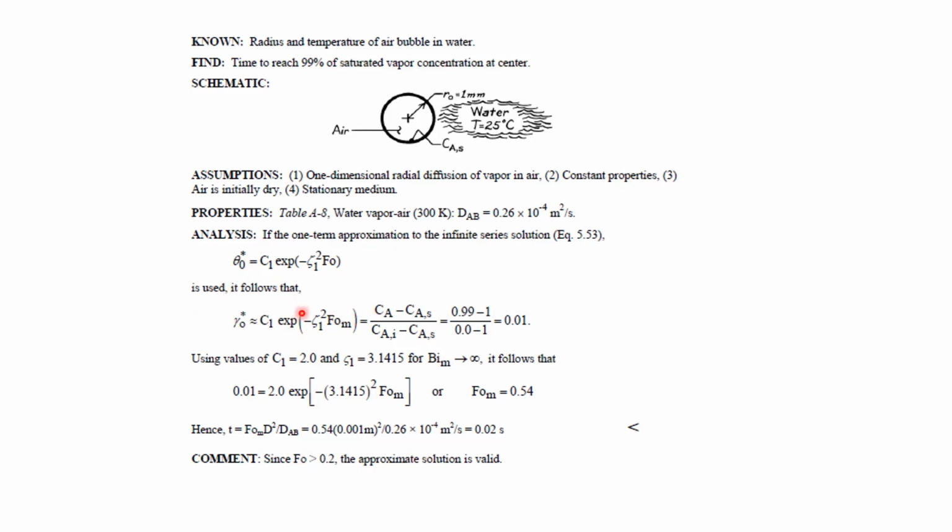So you have seen, I think, the transient cooling of a sphere in air or something. In that similar kind of case, we mentioned the Fourier number based on heat transfer. There we will check that Fourier number is actually less than 0.1. So what is that kind of analysis called? Any idea what that analysis is called in that transient cooling of a solid in air? So we will check the Fourier number. If Fourier number is less than 0.1, we will call it by a particular analysis. What is that analysis? Anybody knows? You can just leave it in the chat.